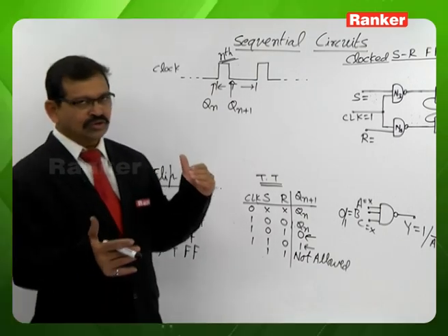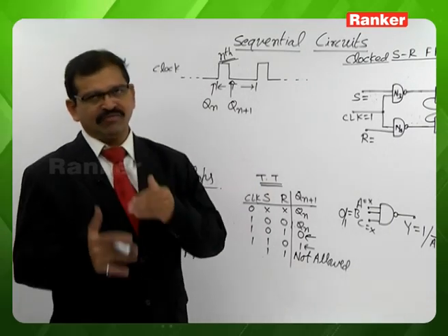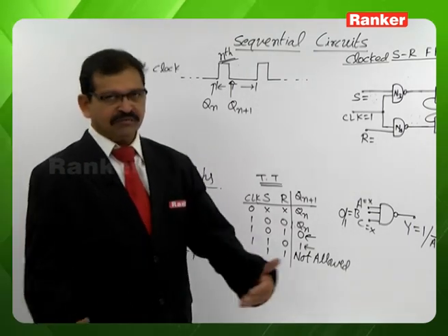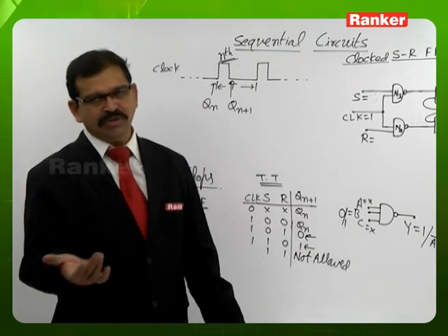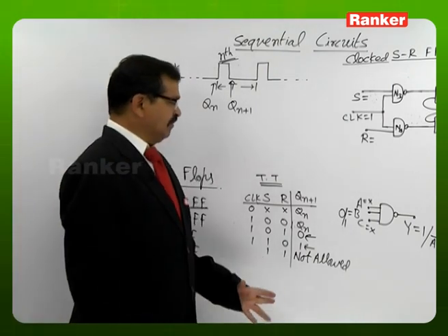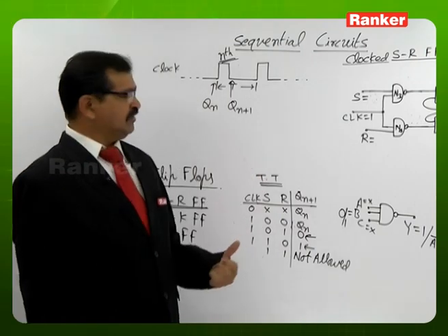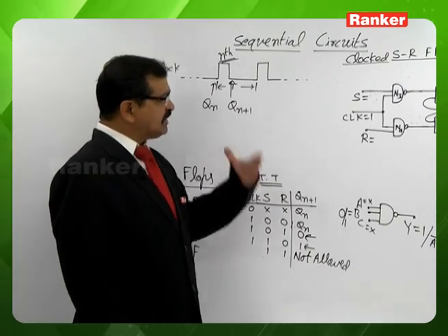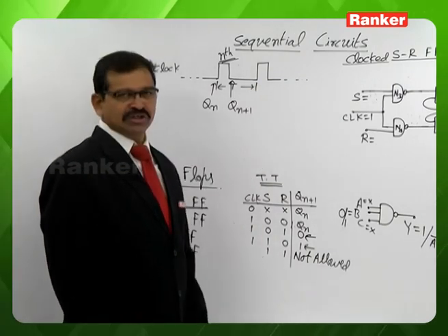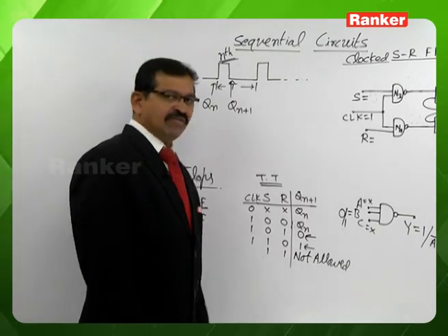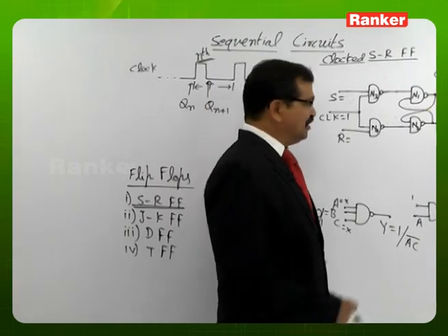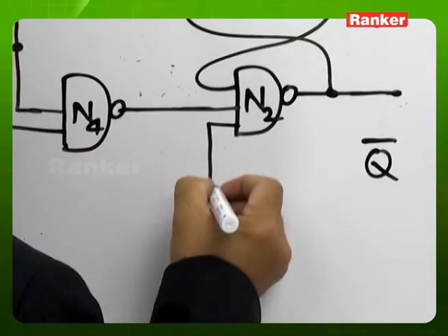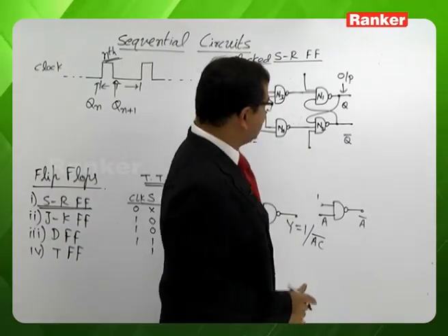Operation of a flip-flop without using a clock, or in the absence of the clock signal, is generally named asynchronous operation. In the presence of the clock signal, the operation is generally named synchronous operation. Anyway, without using a clock signal, we may need a facility to make the flip-flop output 1 or 0. To get such a facility in the circuit, it requires further modification in the hardware. The further modification we are doing is taking gate N1 as well as gate N2 as 3-input NAND gates.